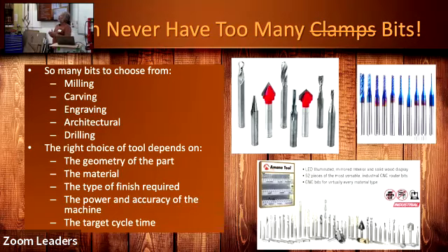Now, is that a tapered ball point, or is that a 1/32? Is that a 1/16? I don't know. Is it an upcut spiral, a downcut spiral, or a compression bit? Well, I don't know, what kind of holes are you cutting? It's not magic, though. There are tables, for lack of a better word, that will suggest what bit you should be using for a particular application.